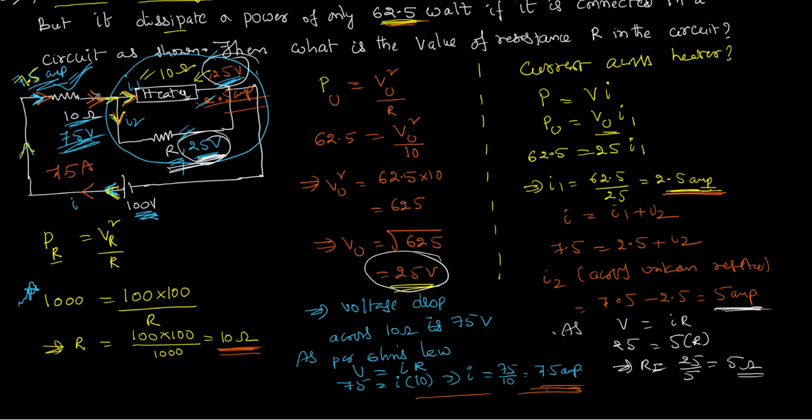While we are solving this problem, just to conclude, we have discussed a lot of concepts, a lot of applications, a lot of understanding that we have to understand a little bit carefully. First thing that we have understood is power has a formula V square by R. This I have already explained in the other video. I have derived it. You can use it. Second point is resistance of a heater is independent of power utilized or power drawn, and that remains constant. Taking that concept into consideration, I have equated resistance and I got the value of voltage utilized.